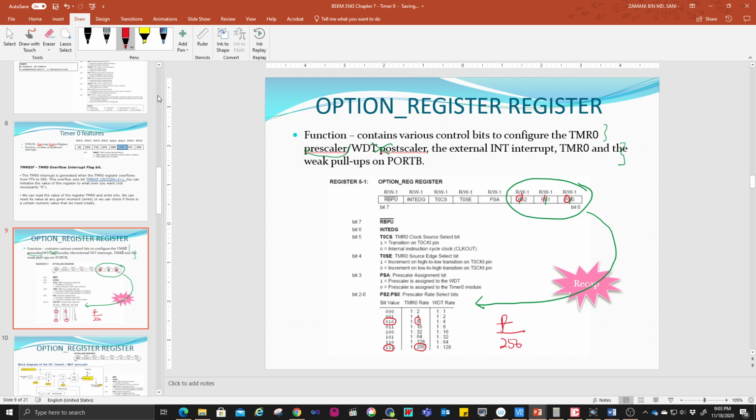You are going to divide the frequency by 8. So this is the prescaler. Without this, you would have your frequency back to normal, 20 megahertz. That's all. It means that if you are using timer 0, you must set this one. Okay, the lowest one will be 000, where you need to divide by 2.